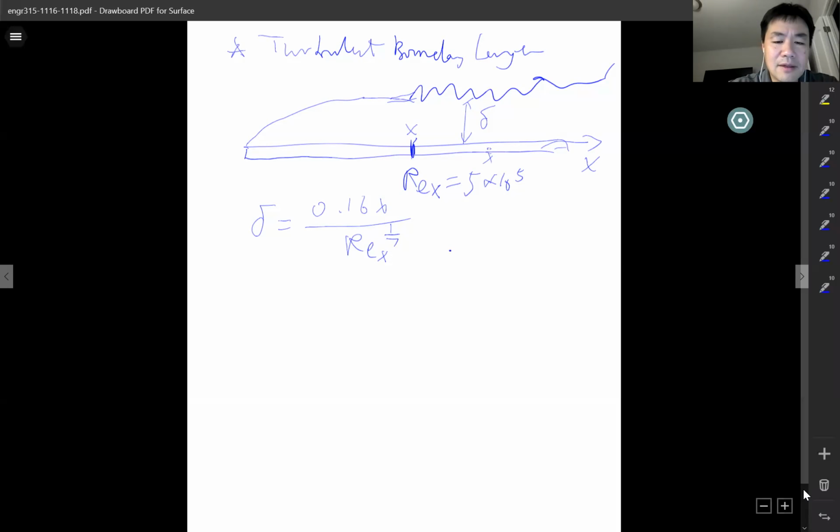Of course, for the flow side, you have lowercase cf equals 0.455 over log squared of 0.06 Reynolds number x. It's also a local value, the local skin friction coefficient. So you can calculate on any location, and you can calculate the local shear stress. Again, when you use the capital CF, that is the average overall CF.